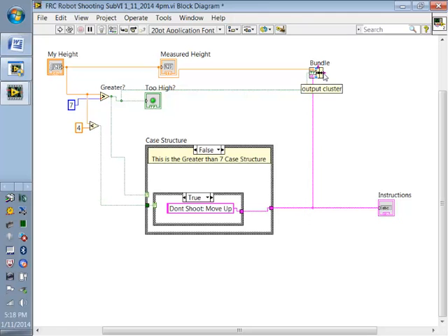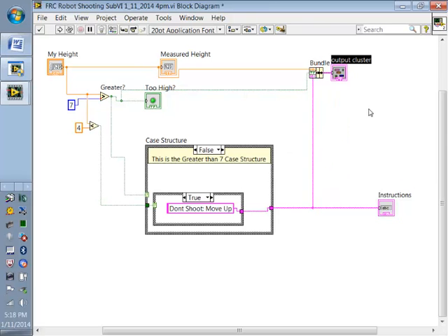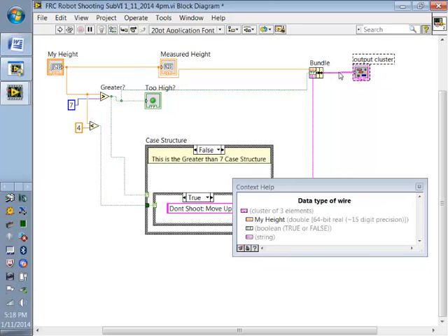Now if I do my trick again and I right click on this and create an indicator, you'll see that, with Control H, there are 3 things on this wire. So you can use Control H to understand what's on a very complicated wire. And any wire that's thick is complicated. Notice that these are all thin wires. Here, thinner. And that's a complicated thick wire.